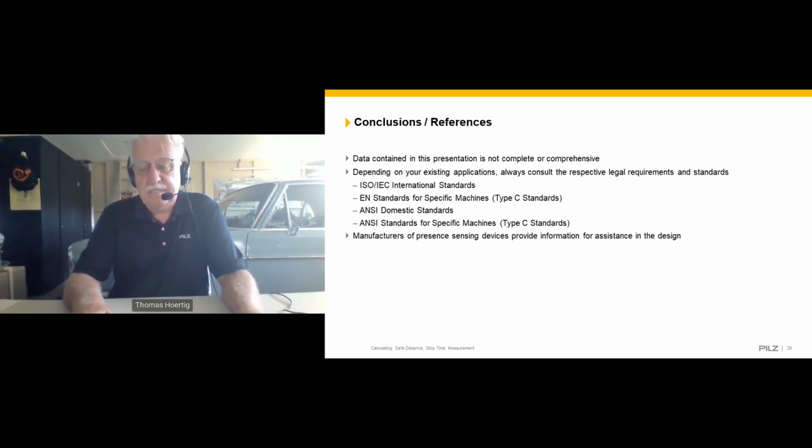Here in the United States, you would look at OSHA 29 CFR regulations. And if you find or need that it's not within in the OSHA book, then you need to consult the respective ANSI standards, the type C, like Charlie standards for the respective machine type. Also, look at ISO and IEC standards or EN standards for specific machines.